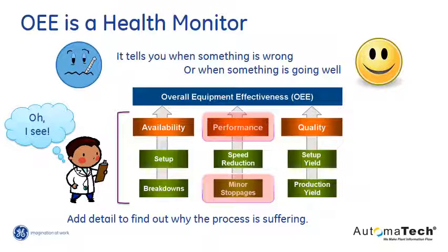So you can see the next layer underneath OEE is availability, performance, and quality. All we're really doing is taking that calendar time of a shift and breaking it down to the different reasons why we're having issues. So availability is your large downtimes. Well, we had a motor failure today. We had some additional time for changeovers. Maybe that's part of your OEE metric. And then for performance, well, we had to run it a little bit slower because the operator's still learning how to run the machine. Or, as is mostly the case, we had a death by 1,000 cuts.